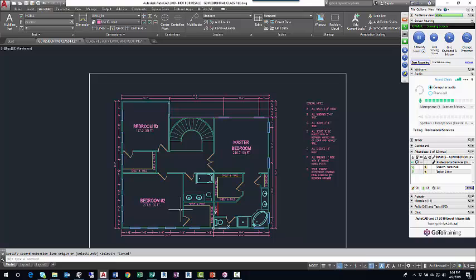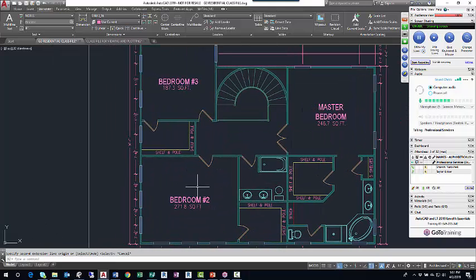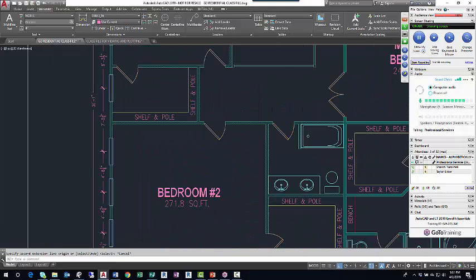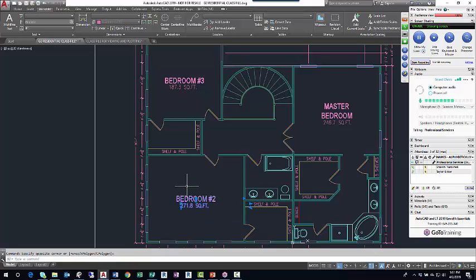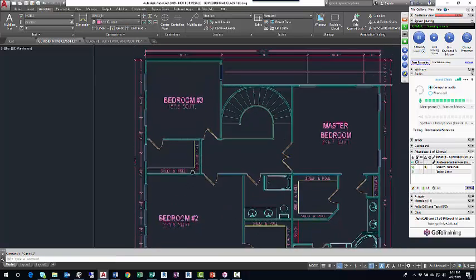So those outside dimensions are really measuring outside corner to the midpoints of windows or outside corners to outside corners. If you choose to do your inside dimensions, those are all wall face to wall face. And I know I've got some stuff in my way. I can move it. Like I'll move bedroom 2 text. I'll select this and just arrow key it over. Control arrow key. It won't be centered, but it'll be out of the way.